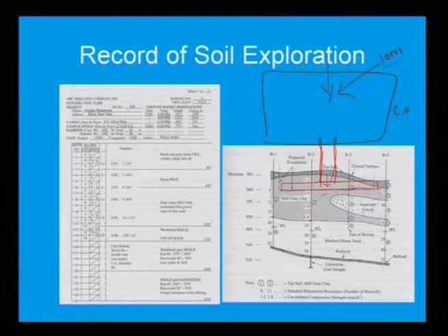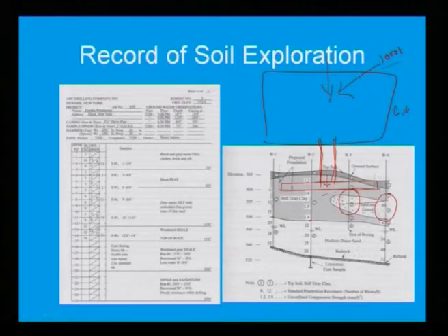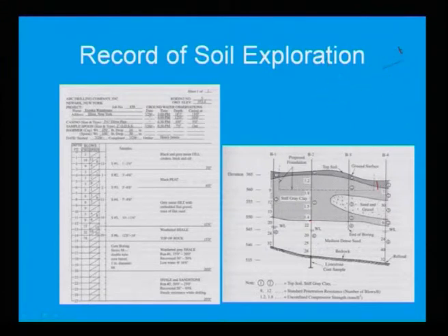So, if you look at this 1 and 2, go to the third and fourth, here you are getting sand gravel, small patches. If you go to the fourth borehole, look at here, the patch will be more. So, this is the basic difference. Instead of laying the footing here, because it is steep clay, where fine grained soils are more, if I bring the footing slightly down, it will lay the foundation over the sand soil, where it can resist more load than your clay soil. So, that is why borehole interpretation is more important for design engineers to decide all these things.